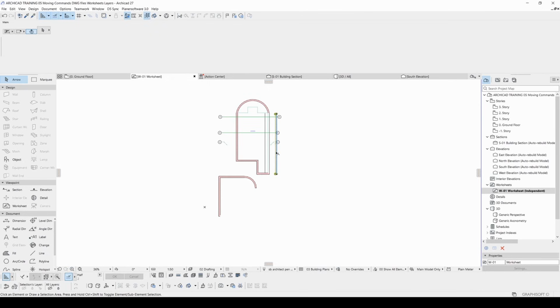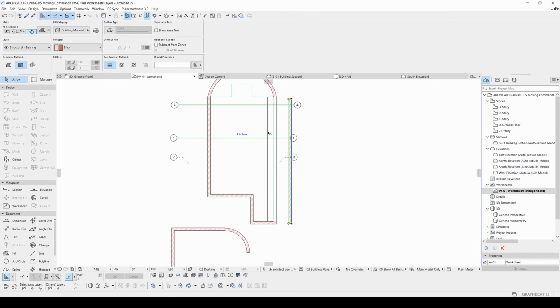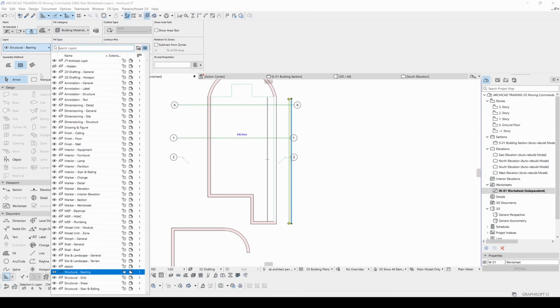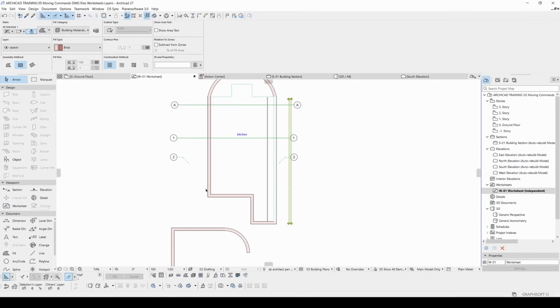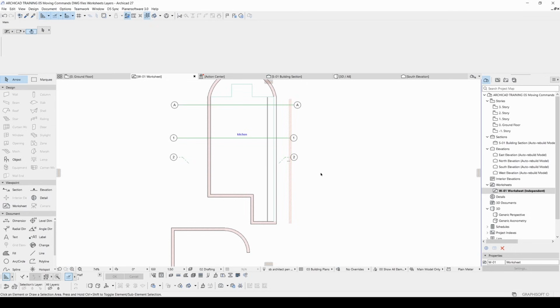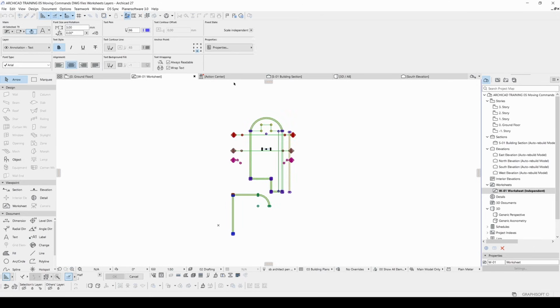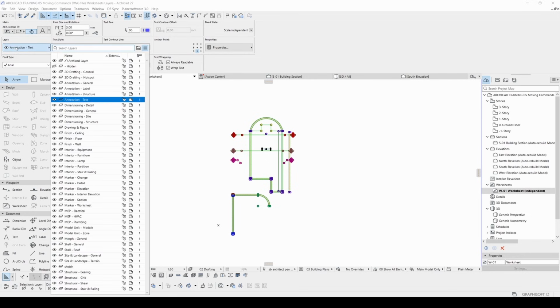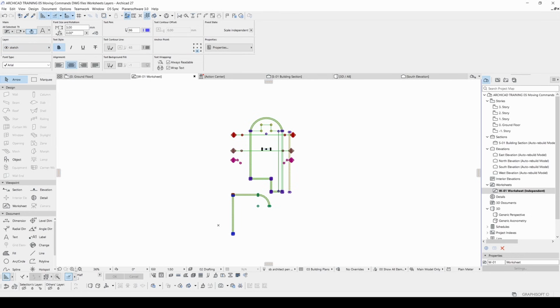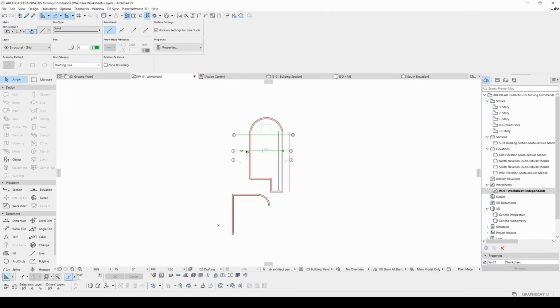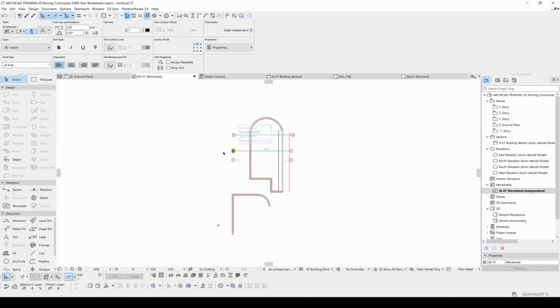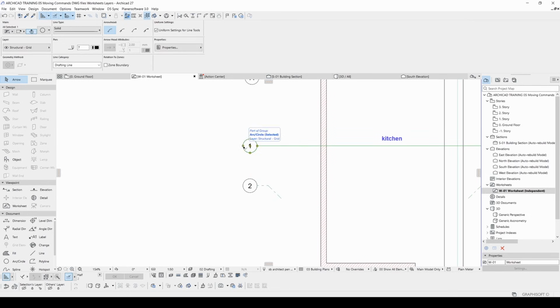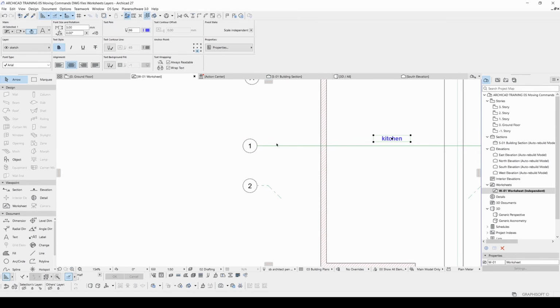Once we have done this, we can click our element, and after that we can go to layer and we can select our new layer name. It's now sketch. If you don't want to do this one by one, you can select all of layers, all of lines, fills, and you can change it from here as well. But you will see it won't work. It's still structural grid. Still structural grid. And this is sketch.